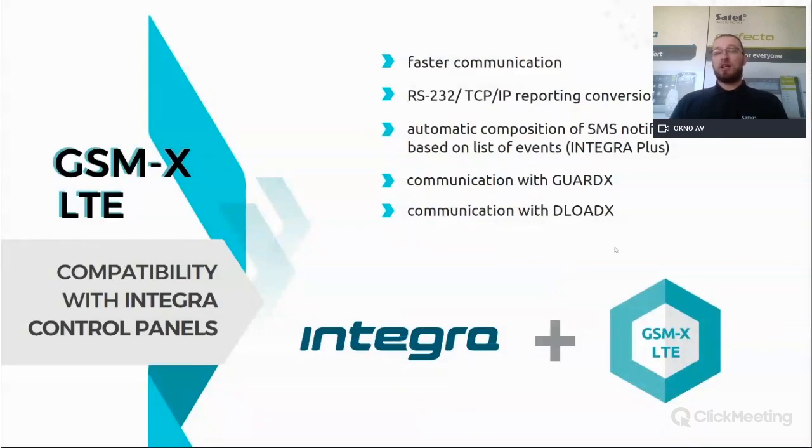But please remember, for Integra, we have INT-GSM unit that is designed to be able to work with Integra. So please, in general, if you have Integra panel, please use INT-GSM, not GSM-X, because INT-GSM gives you more possibilities and easier configuration in general with the Integra panel.